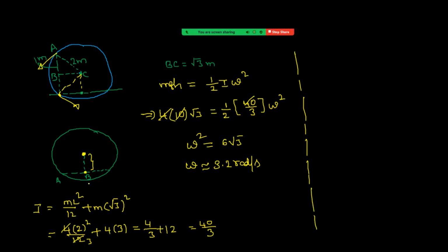That means the velocity of point B. And we know that the rod is in pure rotation. Therefore, velocity equals r omega. R means this distance, how much? From the center of rotation, the center of the axis, the distance is equal to root 3.